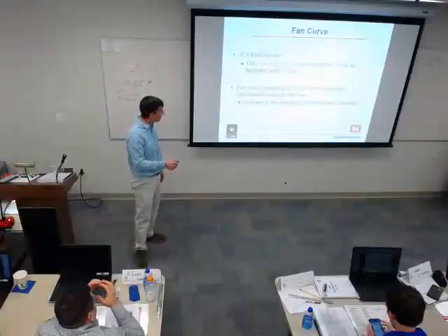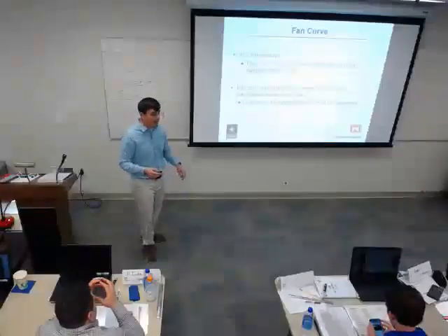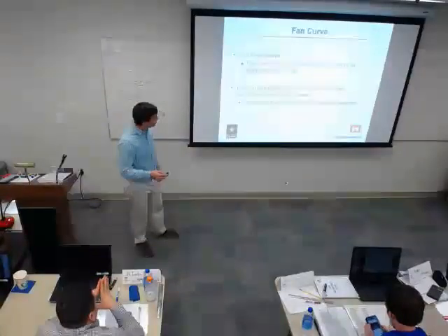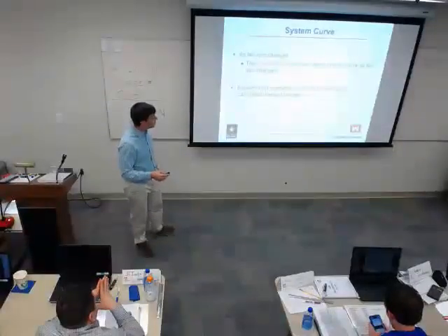The fan curve operating point cannot be predicted. You just have to plot it. You measure the pressure and you plot it on the fan curve. That's different than my system curve.